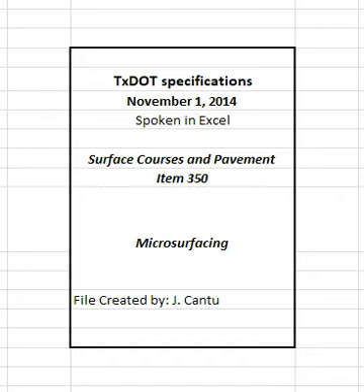4.11.3 Edges. Provide an edge along the roadway center line, lane lines, shoulder, edge of pavement, or curb line that is uniform and neat in appearance. The edge is considered acceptable when it varies no more than plus or minus 3 inches from a 100 feet straight line on a tangent section, and it varies no more than plus or minus 3 inches from a 100 feet arc on a curved section.